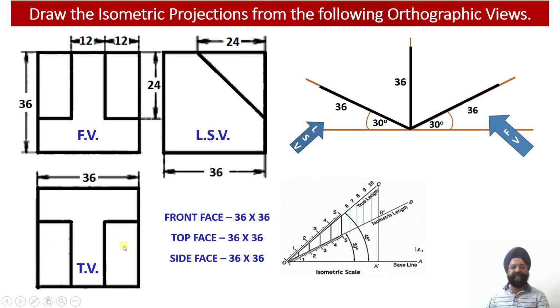How did I decide that these are two inclined webs? On the sides, on either side of this vertical web over here. So this is a vertical web. This is the horizontal face of this vertical web which will be lying at the top over here. So this is the vertical web as it appears to us from the front view. This is the horizontal web which is lying at the top face. So we can conclude over here that at the center there will be a vertical web which will be running across the entire width of the solid over here.